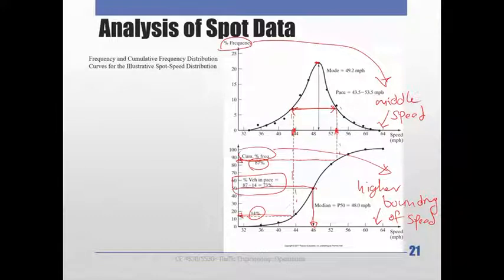For the variance, look at the 15th percentile and the 85th percentile speeds, and you get these two speeds, and you need to get these speeds actually here. Divided over 2, you get your standard deviation. And if you do that, you will get a standard deviation, I believe, of 4.5, very close to what you calculated mathematically.